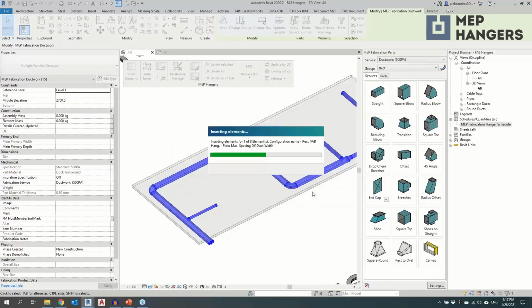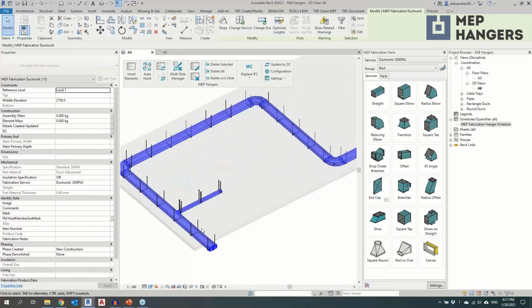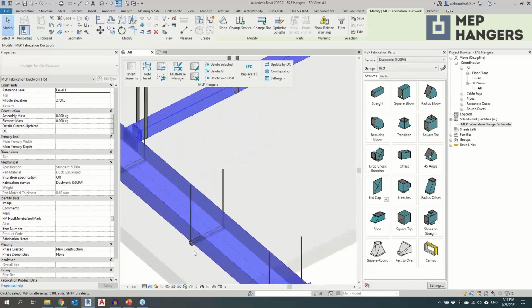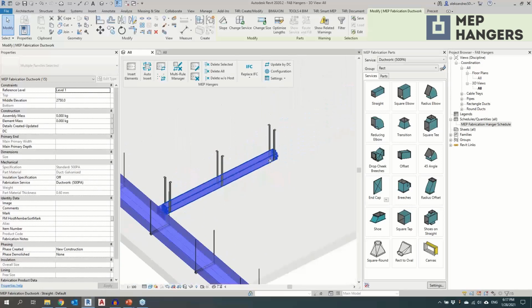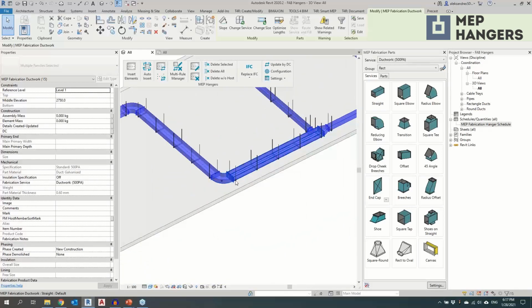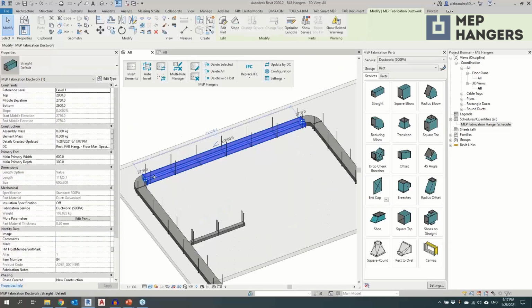And also, I've set in those rules a little bit different spacing between the hangers themselves. And that's the picture that we have, and we had before. Every element has its own hanger. And in this way, 10 rules is pretty much enough to describe any kind of connection of the system inside of your project. Right now, hangers are placed every 2 meters.